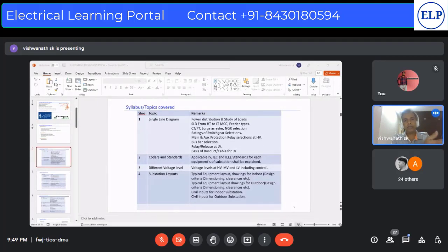Emergency loads always work during normal power, and after that they switch over to the DG set. Process loads are very important from the process point of view, as all of you know. Non-process loads are things like ventilation, air conditioning, welding. In terms of process, the conveyors, a little bit on the production side. So these are related to the process loads.